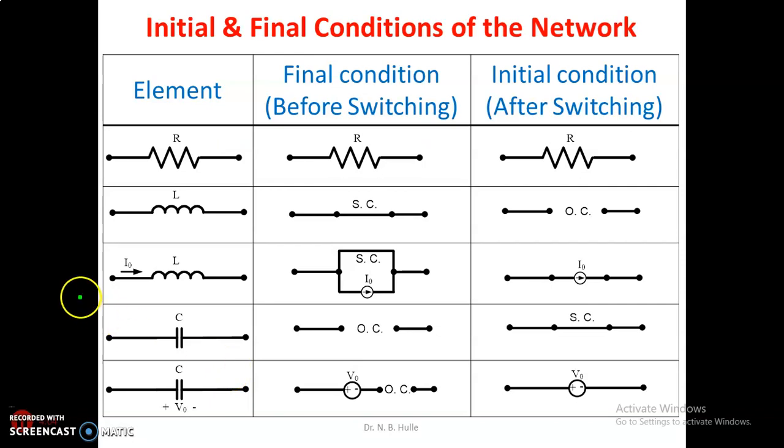Now here, whenever we are taking the case of the inductor, the final condition, that is before switching, it had reached the steady state, and in the steady state or in the final condition it acts as a short circuit, and in the initial condition it acts as an open circuit. I will discuss this case first and then I will come back to this original slide.